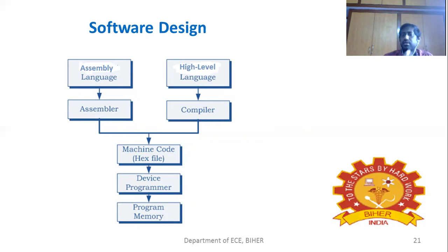For example, the 8085 microprocessor is there, and the 8086 microprocessor is there. The first one doesn't support direct multiplication, so we cannot directly use a multiplication instruction for that. The programmer must know about that. The 8085 won't support direct multiplication, so we need to write the code in terms of repeated addition. So hardware knowledge is very essential for an assembly language program.